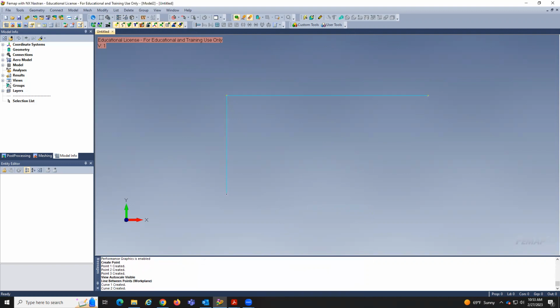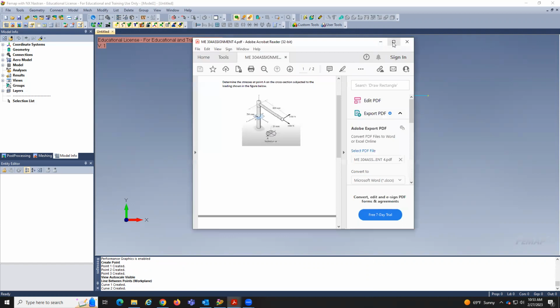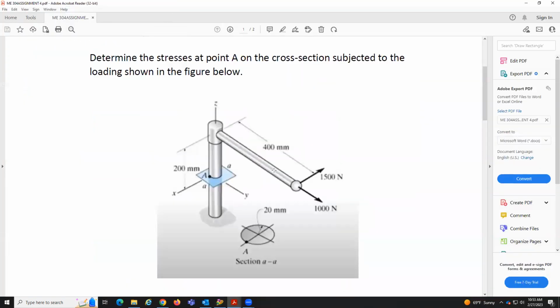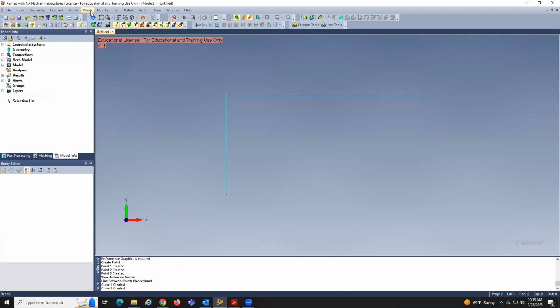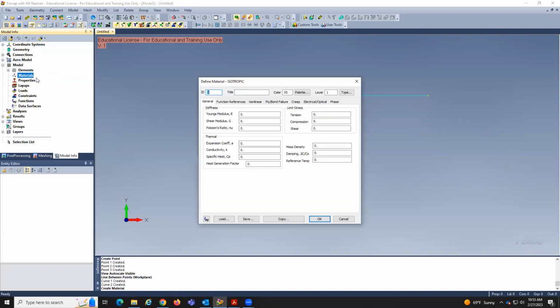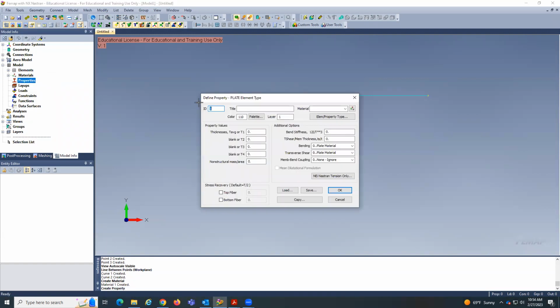So this is basically this part of the beam. Now we need to apply the loads at the tip. So let's say, oh, not yet. First let's mesh. We don't really use the material, but in order to run, we need to define a material. I know this is still in millimeters, so this would be 207, 0.3, but you can put any value here because we are not calculating deformations. Cancel, properties, new. We select that material.